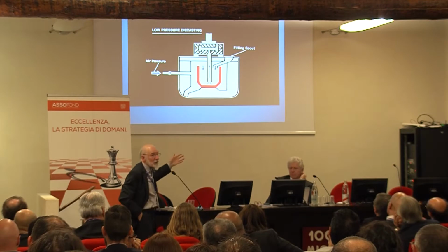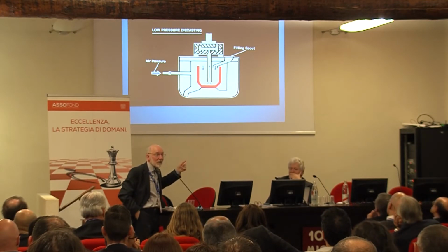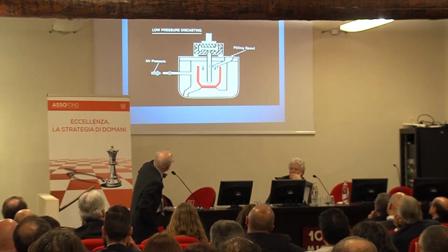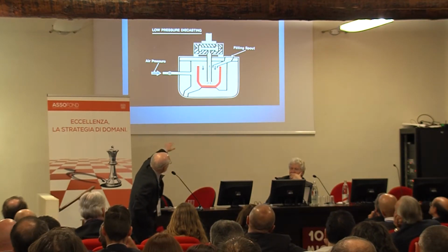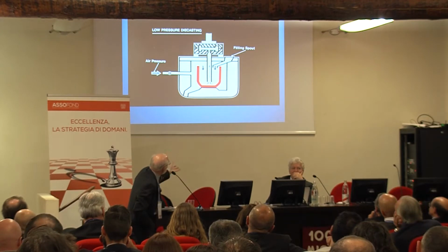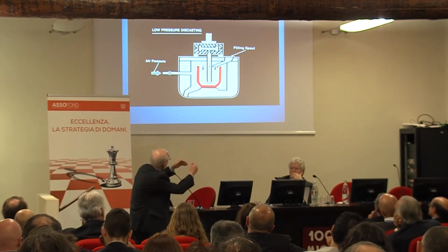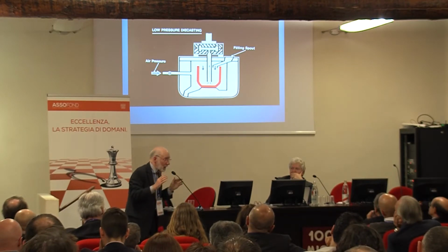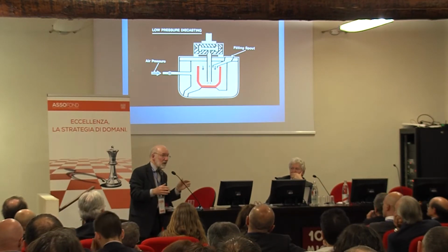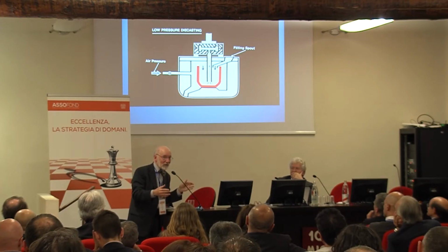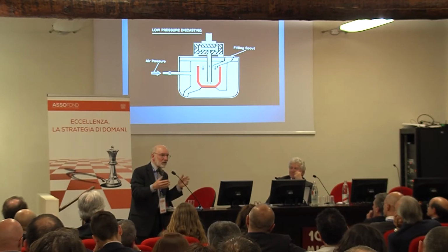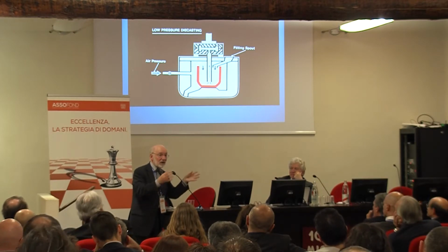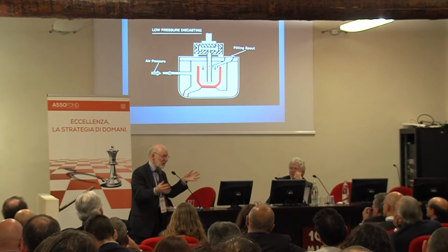So you'll all know about low pressure die casting. Most of our wheels are made this way. And we put a pressure into the pressurized furnace. The metal lifts up the spout. It goes up the spout in the correct way, into the mold in the correct way. But the product is awful. And all of our wheel makers struggle with the quality of the product because of the prevalence of bifilms. The metal is just full of bifilms.